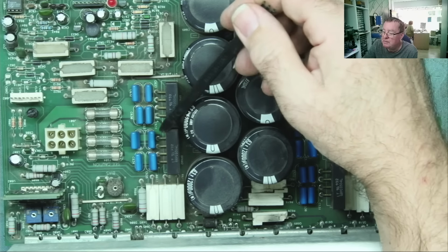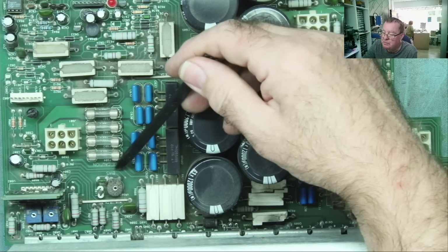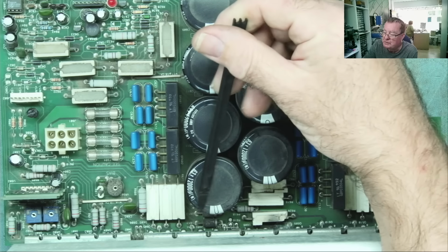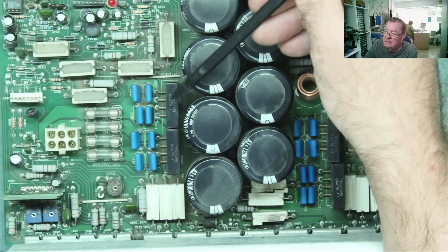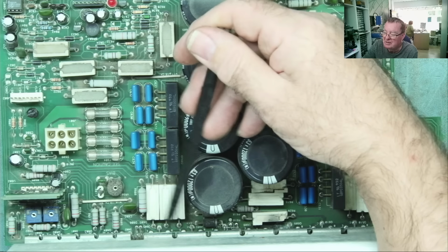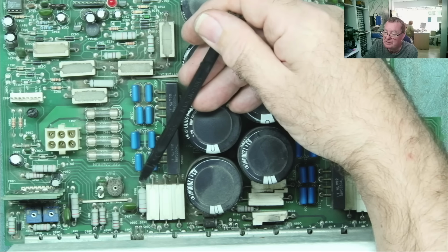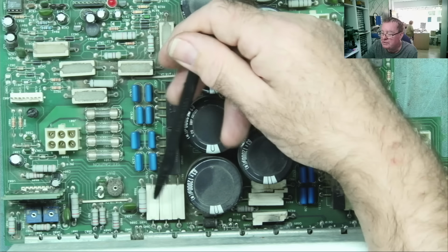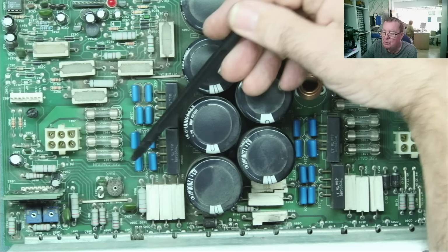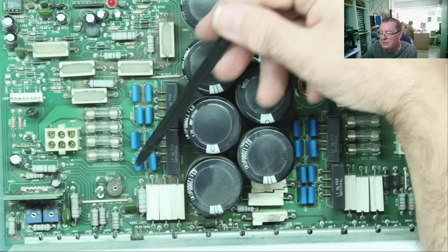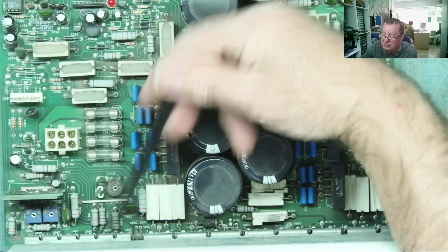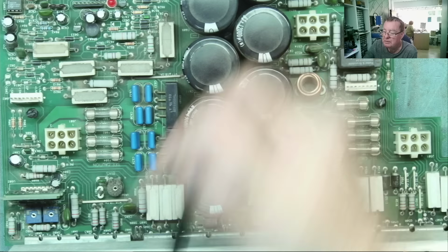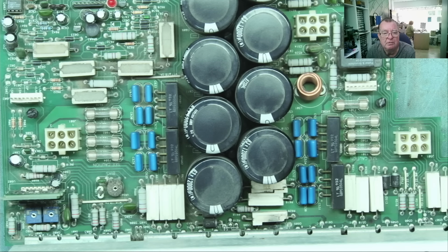And bear in mind, particularly in amplifiers, there'll be one of these which balances the output of the amplifier, the offset, so that when there is no signal coming in, the output transistors are basically idling and the output voltage is basically 0. If they fail, then they can quite often take the output transistors with them, because all of a sudden there's a big offset voltage, and the output transistors and the ones that drive them, and maybe the ones that drive those, can fail due to one of those. So they are something definitely to keep an eye on that will fail.